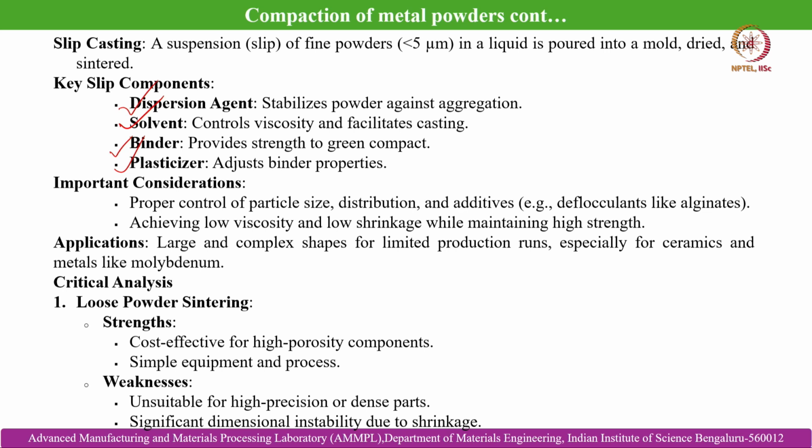So, the loose powder sintering strengths are that it is cost effective for high porosity components, with simple equipment and processes. Weaknesses, of course, are that it is unsuitable for high precision or dense parts, and there is significant dimensional instability due to shrinkage.